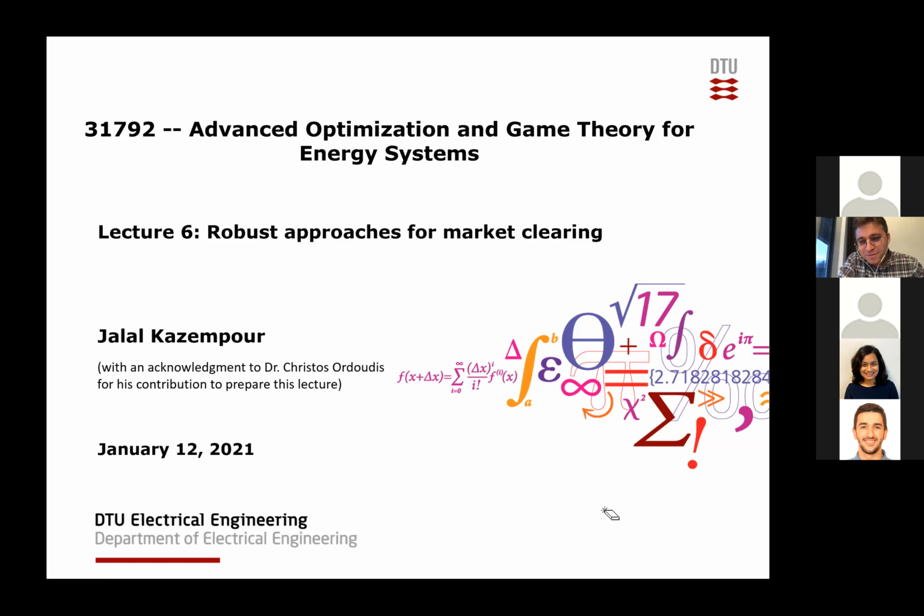And in the scenario with the highest wind production, we have 10 megawatts spilled because we don't have a down regulation resource to absorb the additional wind power excess. And in scenarios 2, 3, and 4, in all of them, we have a cost reduction in real time because G2 doesn't need to produce anymore.